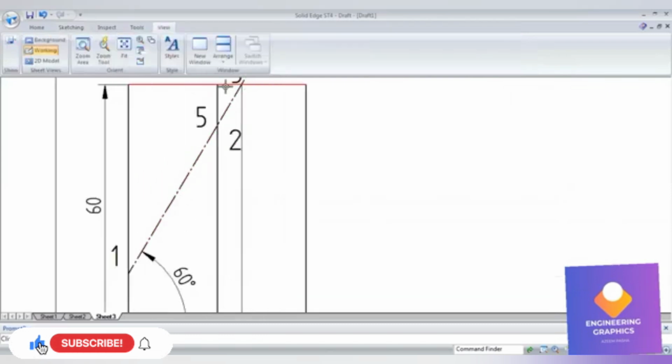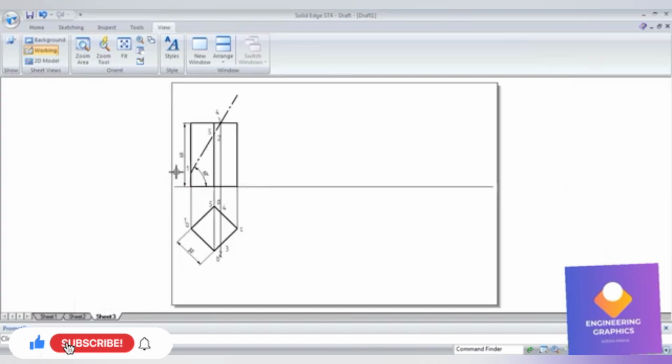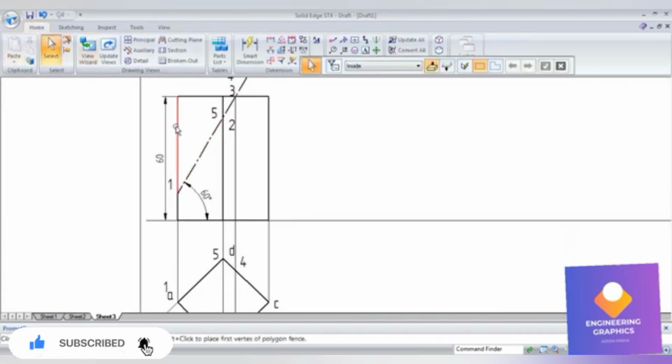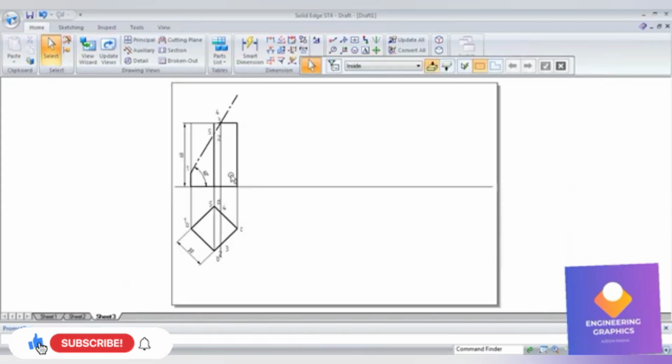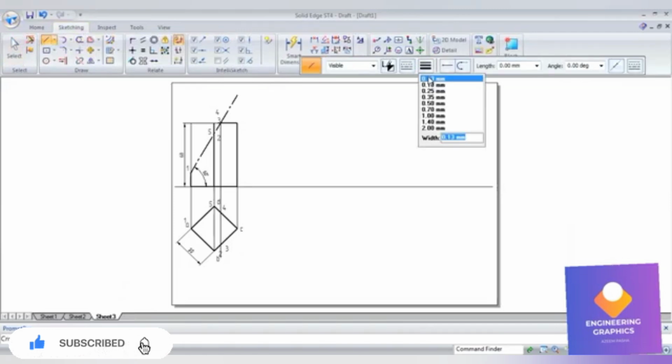I can use the split command to highlight only the retained cut portion. Using the split command, we can split it exactly where we want to make the lines dark. We have to make dark only the portions which have been cut by the section plane, the retained cut portions. The other lines I'm going to make thin lines, by selecting these lines. Now we got the cut portion.